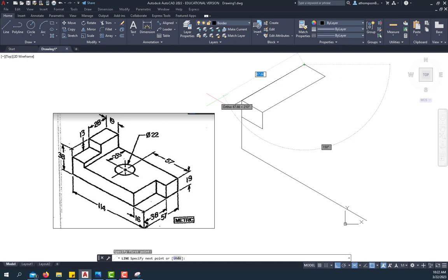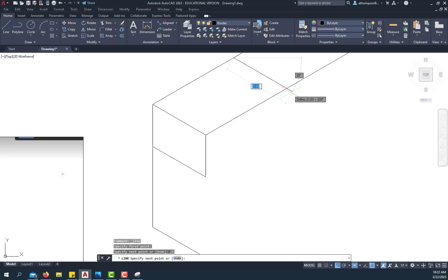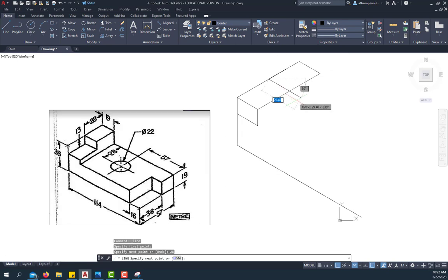But this is 28 if we're following our dimensions. So 28, enter. I know it comes out here. I really don't want to snap to the midpoint because half of 57 is not quite even with the full 28. So just bring it on out and we can trim.